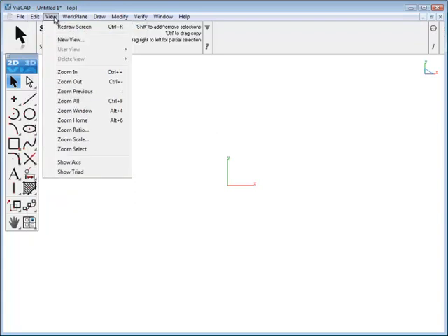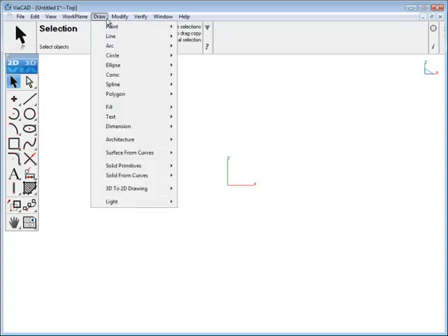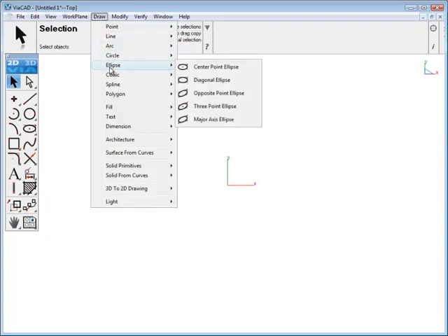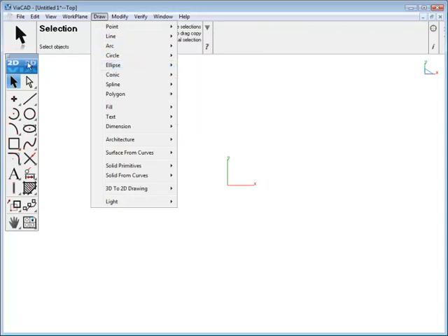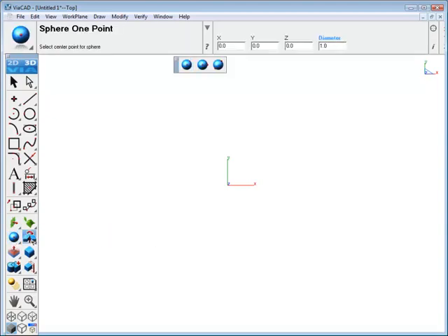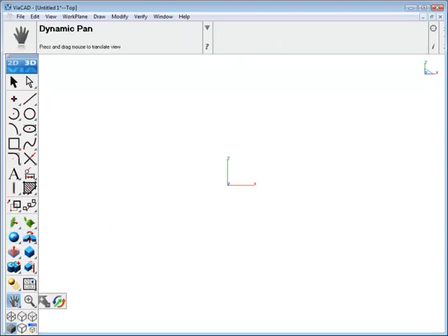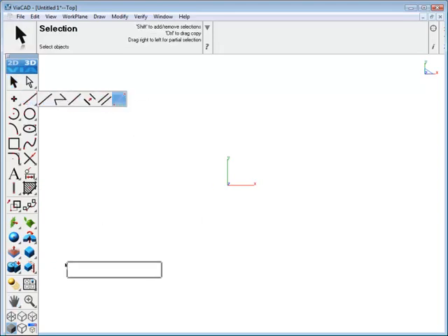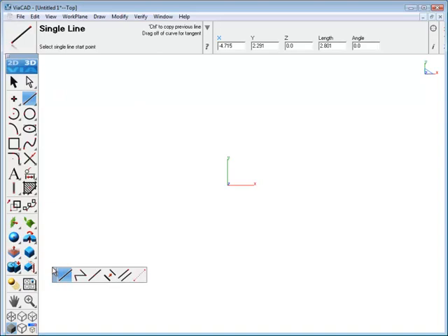This may be because an object must be selected first. To switch between 2D only mode and 2D and 3D mode, click on the title of the main tool palette. Now notice that a variety of 3D drawing and editing tools are available: 3D drawing tools, editing tools, and navigation tools. Drag the cursor out past the last tool in the tool palette to tear off the tool palette and have access to all of the tools at one time. And just click to close them.